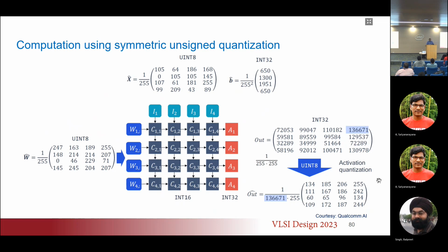If I remember correctly, in the Qualcomm framework, for example, they create a file of this neural network model, which is called a DLC file. In the DLC file, they already take the model, chunk it up into tiles, and provide instructions as to how these tiles should be loaded and executed. So on your mobile phone, when you're doing Hey Google or OK Google, that model is already downloaded to your phone, with the instructions as to how to do tile by tile computation.